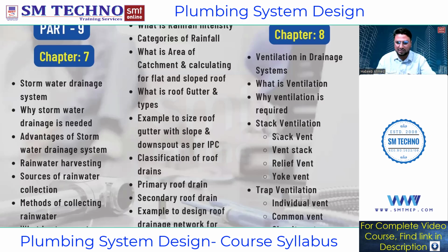So what do you mean by stack vent? What do you mean by vent stack? What do you mean by relief vent? What do you mean by yoke vent? This all comes under stack ventilation. That means the ventilation, or exchanging of air, happens only with the vertical pipe. We'll be discussing the stack vent, vent stack, relief vent, and yoke vent.